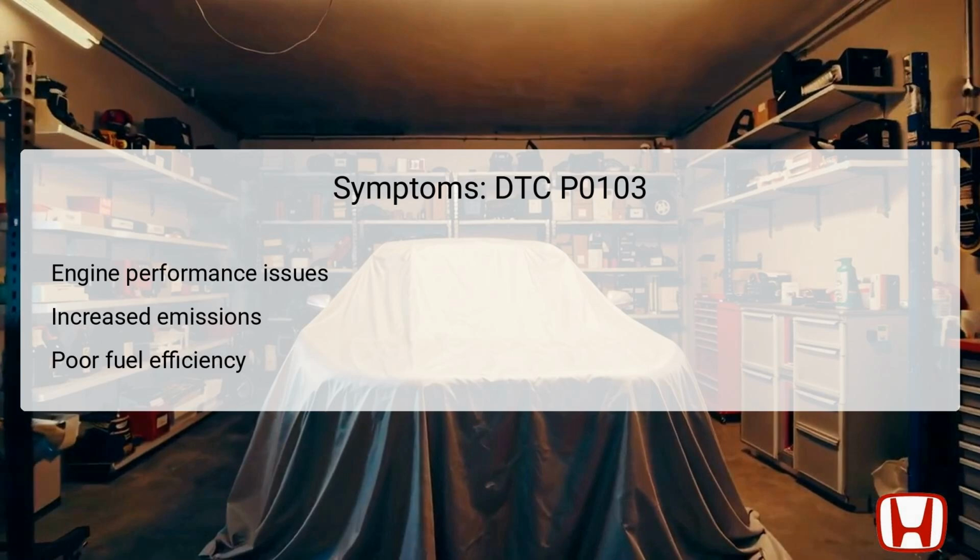Additionally, you might observe a drop in fuel efficiency due to the engine compensating for perceived inaccuracies in the air intake. These symptoms could also lead to further complications if left unaddressed. Technicians should remain vigilant and conduct a thorough diagnostics check upon identifying these symptoms.